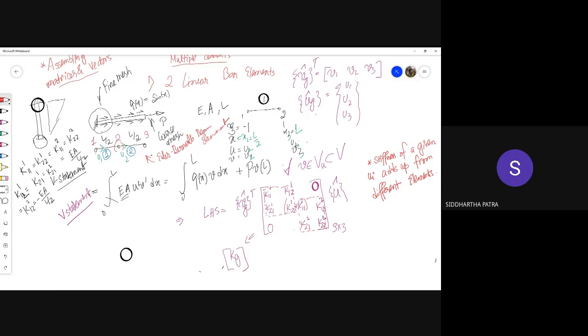Okay, also imagine in 2D two triangular elements. This one has 3 nodes, no mid-side node, so only corner nodes. If two triangular elements are connected, obviously they would be connected by a total side, which means there would be 2 nodes. And also in 2D there are 2 degrees of freedom, so you can move in x and y per node.